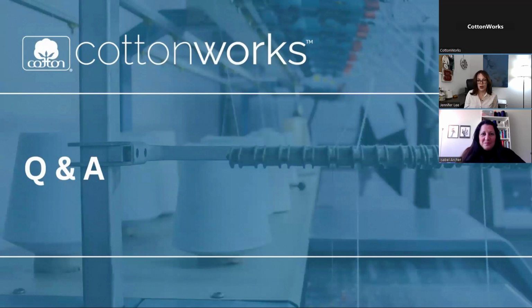Thank you. So a couple questions about limitations of flatbed knitting. What are the restrictions regarding the amount of colors that can be used in a garment? So flatbed machines generally have between 16 and 32 yarn carriers. We normally reserve a couple of those for casting on and for draw thread yarn. But then the rest of the feeders you can use to your heart's content for as many different colours or textures as you like.